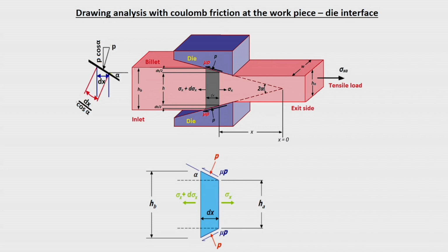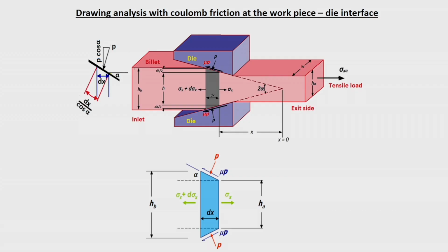So, your mechanics of this metalworking. Maybe this is similar to what we discussed in the mechanics of metalworking, but there we just discussed the case of a slab method, where the load necessary for just homogeneous deformation of the material is considered inside a frictionless die, and where redundant deformation also is not considered. So, here let us take the case where, because in practical application there is going to be friction at the workpiece material and the die interface, you have to consider the friction also.